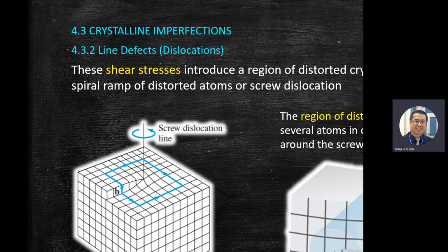But the Burgers vector is parallel when it comes to screw dislocation. Okay. So how do we test your understanding between edge and screw? Sometimes we give you a statement of how the atoms move when you process material. Then we ask you to predict the type of dislocation that happens.